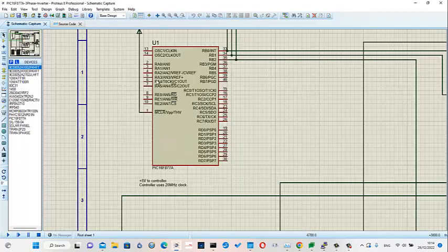The microcontroller is used to generate a clock signal, and as this is a three-phase design, it is the basis, the building block of a more sophisticated design capable of serving multiple customers. We are going to use three-phase. Individual dwellings and small commercial premises would only be connected to one phase. So I need to generate a clock signal for each of the three phases with a high degree of accuracy at 50 cycles per second, 50 Hertz.